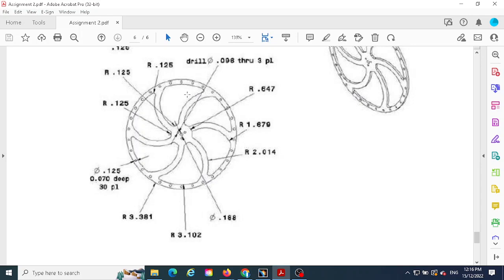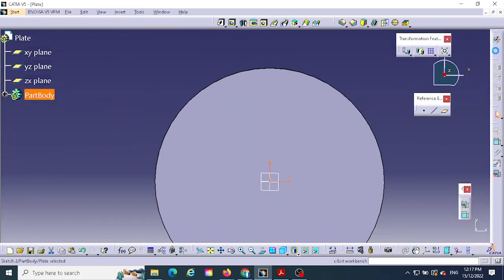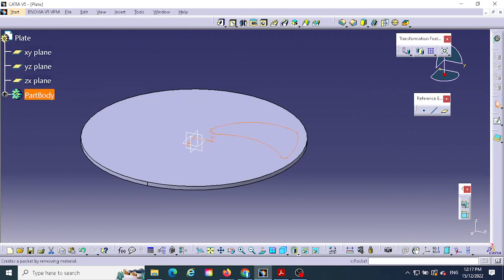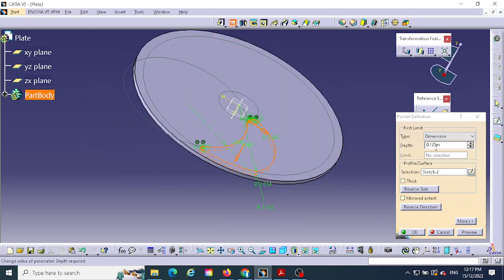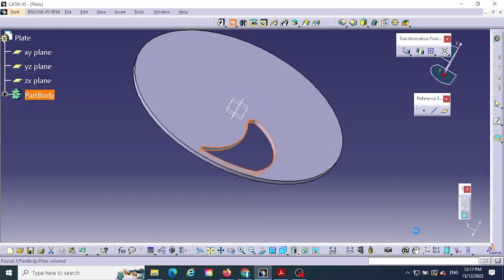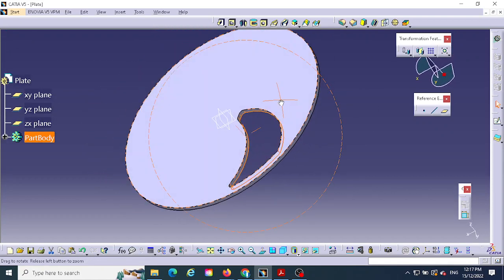So what I do is I just make this an extrude, I mean the cut. This one, I create this one. In CATIA, if you just go out from here, as you can see, I use the extrude cut or pocket. In SolidWorks it is extrude cut, this one is pocketing. So I just click here. You can see here the pocket is already made. It's 0.5, the thickness of this. So you just say okay, right? So I created already this one. This is a profile here.